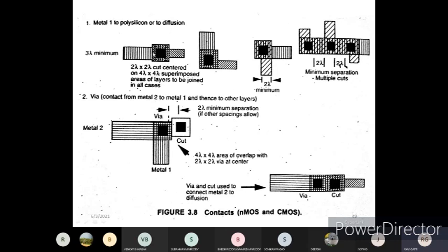So you can see here polysilicon to N-type diffusion material. How can we combine those two layers? We can do it with three approaches. Once again, I am telling you, three approaches we can make. One is polysilicon to metal, and then metal to diffusion contact. Or we can do the buried contact between the polysilicon and diffusion, and also there is one more contact we can establish,